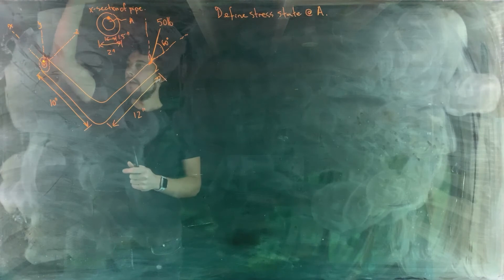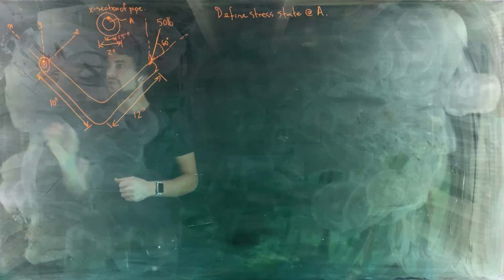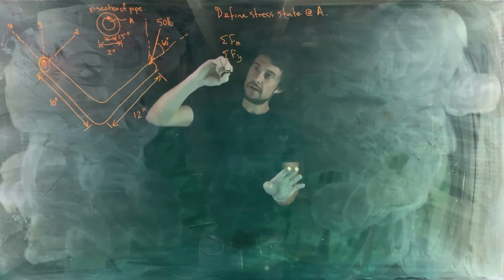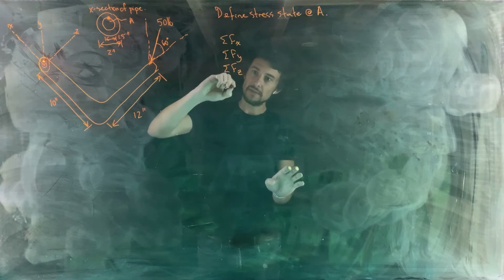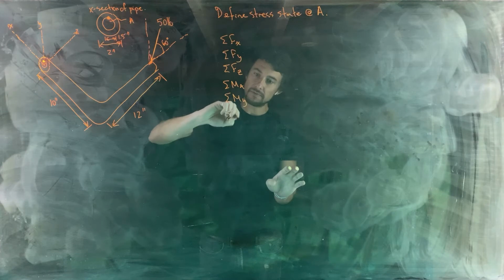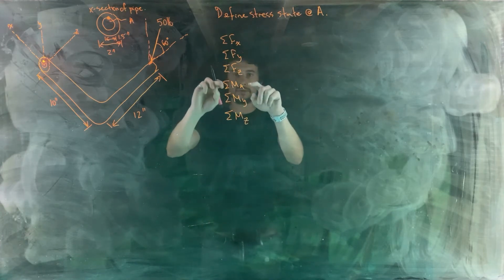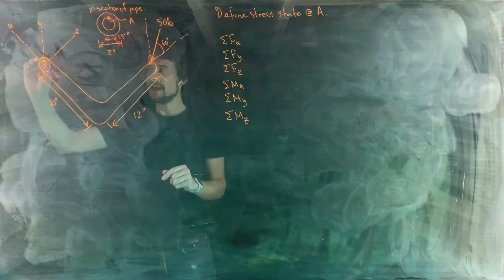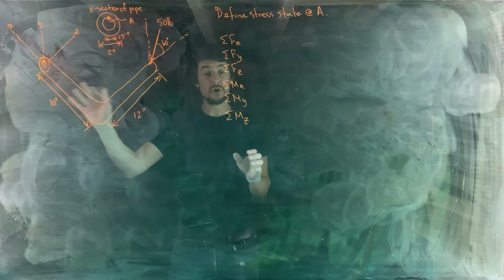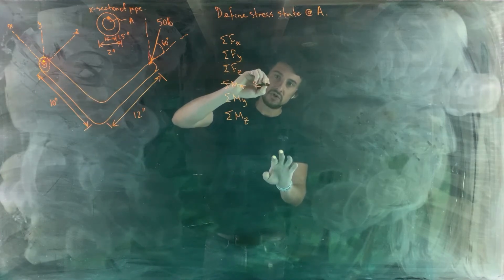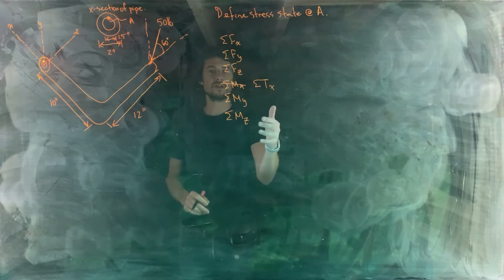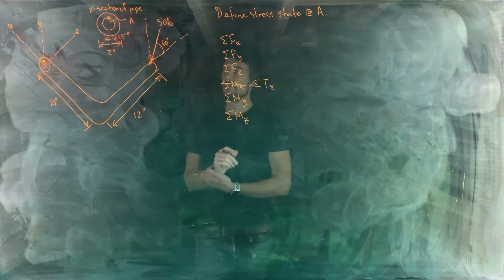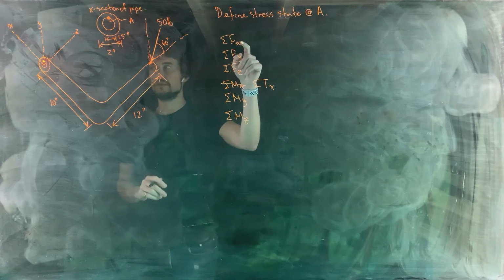Okay, there we go. Turning this into a free body diagram. So now this is a cut edge there. And again, helpful, I think, to write out all the equations that we're going to apply. So sum of the forces along each axis, and then sum of the moments about x, sum of the moments about y, sum of the moments about z. And then we look at the moment equations and say, hold on, the longitudinal axis of this pipe is the x-axis. So any internal moment that occurs about the x-axis is not a moment, it is actually a torque. So this should be sum of the torques about the x-axis. And all of these things are equal to 0 if this is in static equilibrium, which it is. Okay. So let's go through them one by one. So sum of the forces in the x direction.